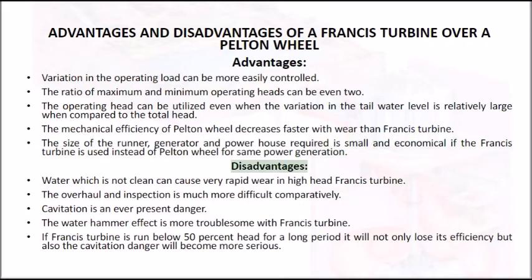Disadvantages: Water which is not clean can cause very rapid wear in a high-head Francis turbine. The overhaul and inspection is much more difficult comparatively. Cavitation is an ever-present danger. The water hammer effect is more troublesome with a Francis turbine.